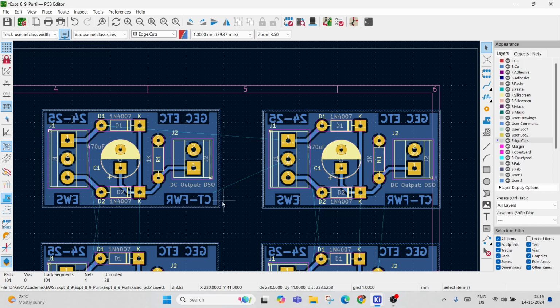So I require some body in between, 2 mm of PCB, so that the edge cut happens through the PCB, and not between air and PCB. So I need at least a 6 mm gap between two PCBs vertically and horizontally, and I feel I need at least a 2 mm gap at the edge, because there are going to be clamps on the side.